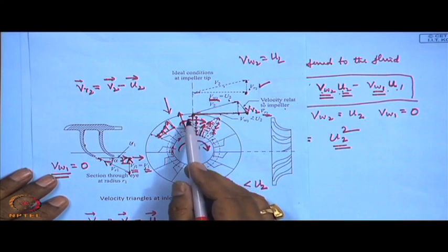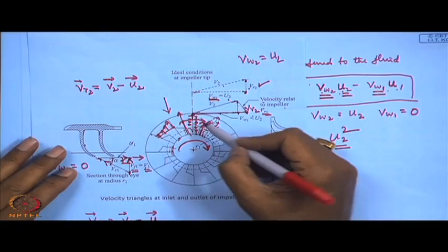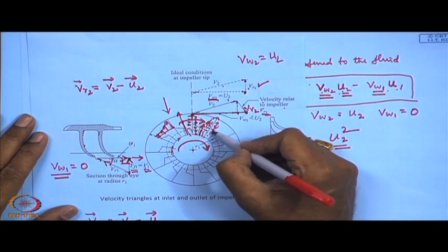So this is the slip, but you have to know the fluid mechanical principle of slip. It is because of the blade curvature and the rotation of the blade, the motion is being imparted to the blade. At the same time the fluid flows past the blade on the two sides of the blade, leading edge and trailing edge, which creates a sort of a circulation combined with a linear flow in the radial direction, which creates this type of difference in pressure and a local recirculatory flow.